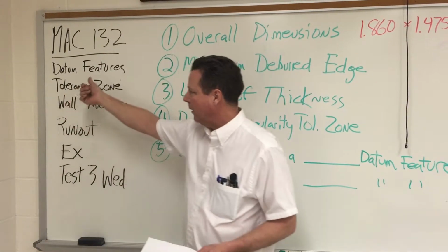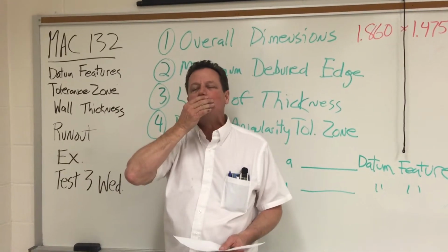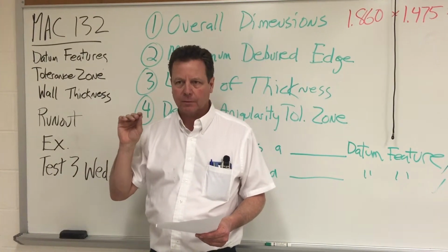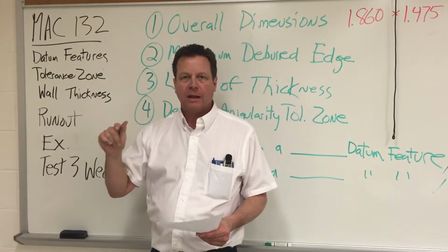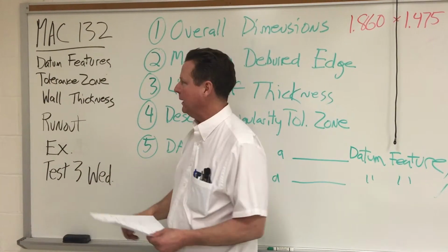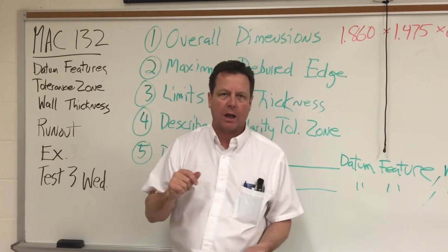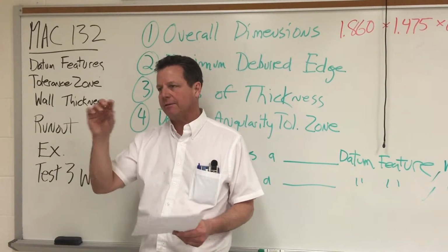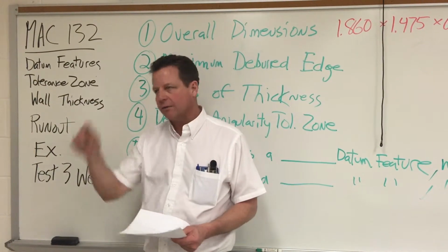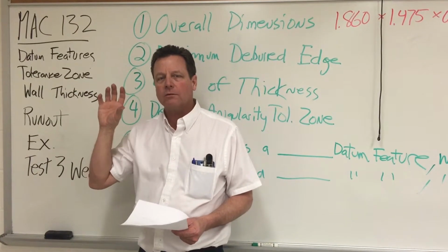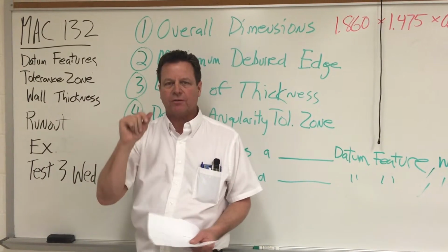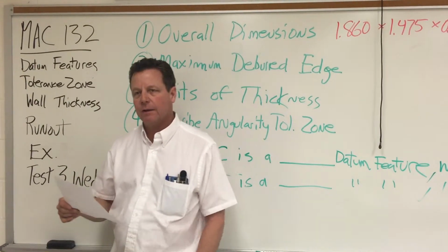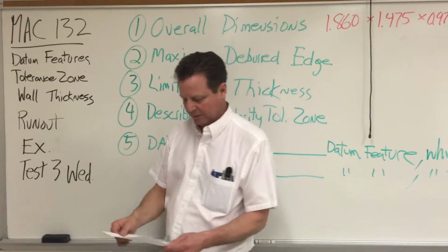So what we said was, if you can see that a dimension has a datum callout attached to it, and there are dimensions there, then it is going to be an axial or center line type of datum feature. If it's like flatness attached just to a surface and there is no dimensioning or any other callout on it, then it is just a surface datum. That surface of the part is going to serve as the datum for your measurements.